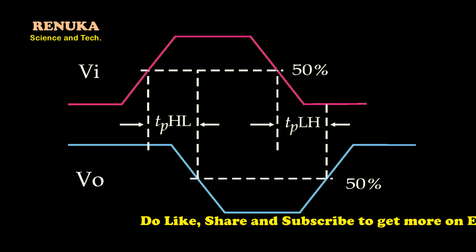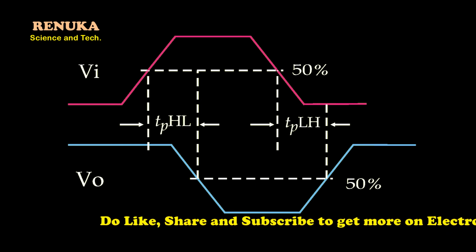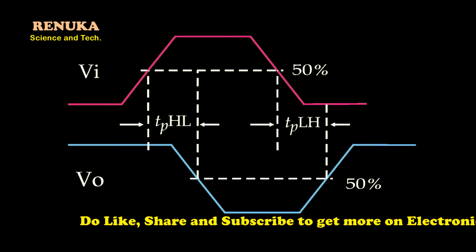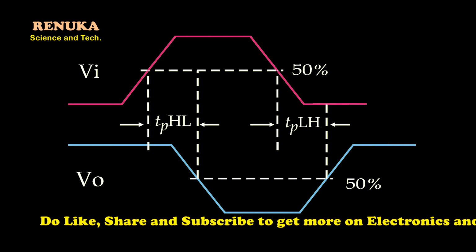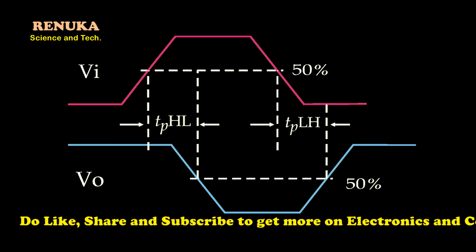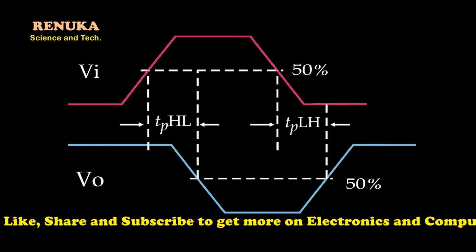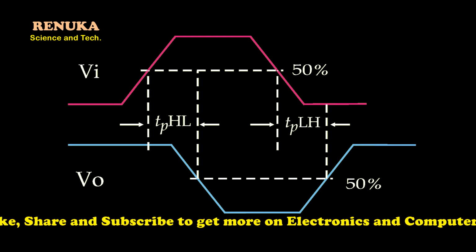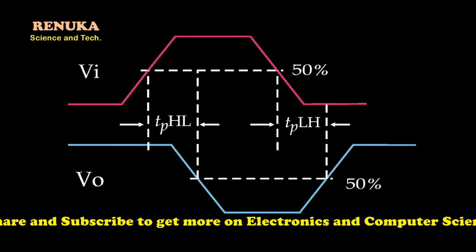Now you can see, if you compare the input voltage and output voltage levels, they are differentiated with a 50% margin, shown by a dotted line at the input and at the output also. So when the input has changed from low to high, the output is changing from high to low because it is a NOT gate.